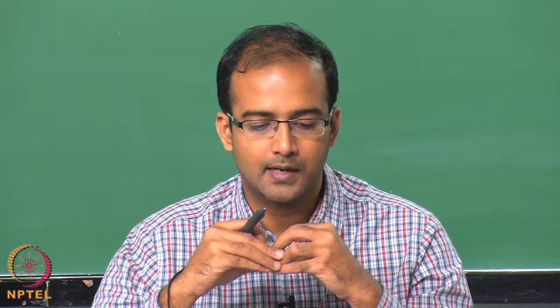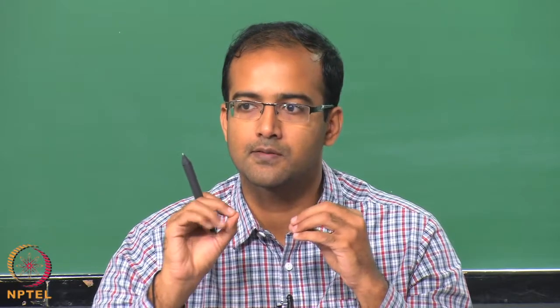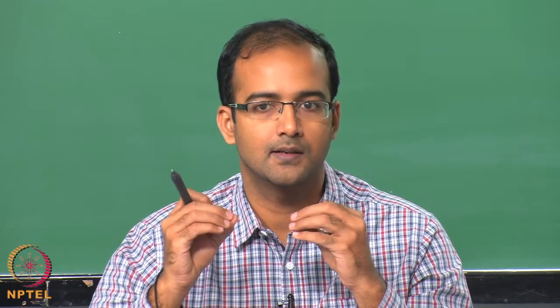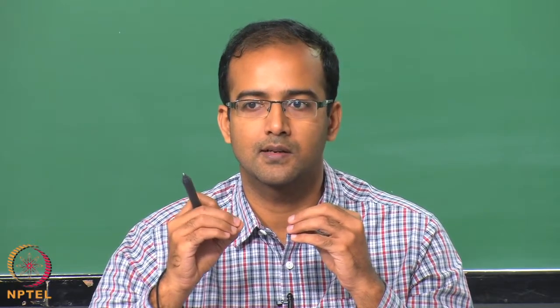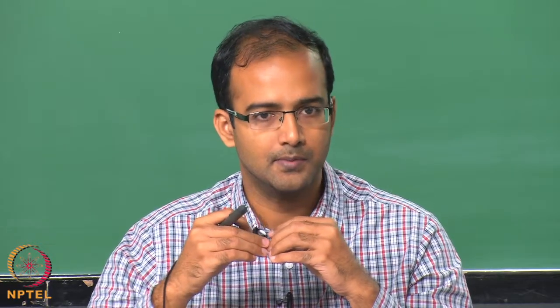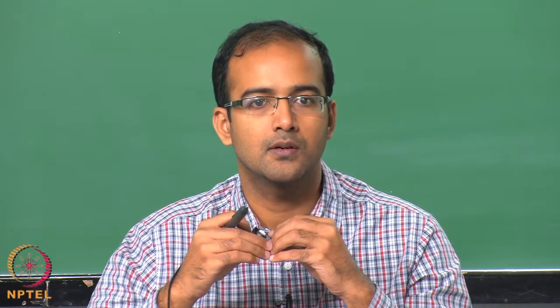Okay. So, the biggest limitation is the fabrication trouble for this kind of micro components, and especially the quality of the surface and micro roughness will play a big role when you are creating this junction. The inherent defects in the material and the surface roughness now will get amplified, right. So, sometimes you may not have a perfect junction, and sometimes this junction may not be uniform in sensing a particular temperature. Some parts may be rough and corrugated. Some parts will have a better contact, some parts may not have sufficient contact. So, this will again lead to problems in accurate temperature detection.